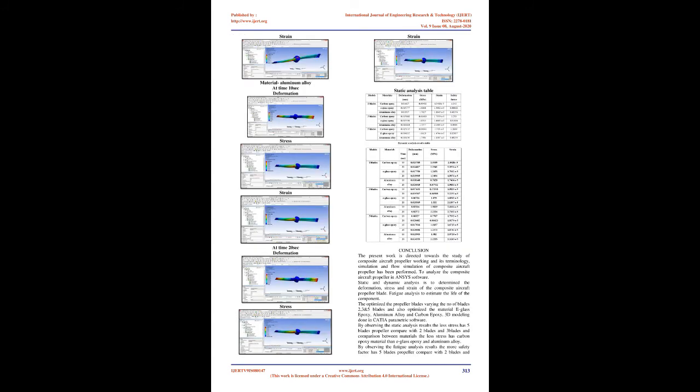Introduction to FEA. Finite element analysis is a method of solving, usually approximately, certain problems in engineering and science. It is used mainly for problems for which no exact solution, expressible in some mathematical form, is available. As such, it is a numerical rather than an analytical method. Methods of this type are needed because analytical methods cannot cope with the real, complicated problems that are met with in engineering. For example, engineering strength of materials or the mathematical theory of elasticity can be used to calculate analytically the stresses and strains in a bent beam, but neither will be very successful in finding out what is happening in part of a car suspension system during cornering.